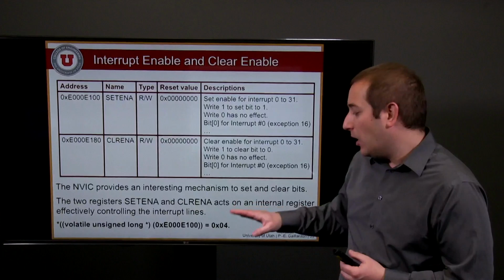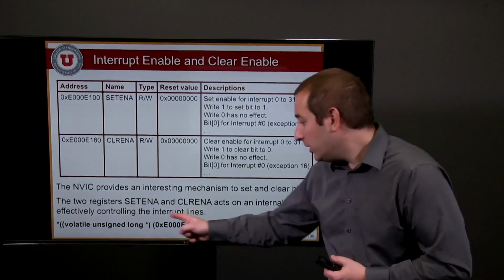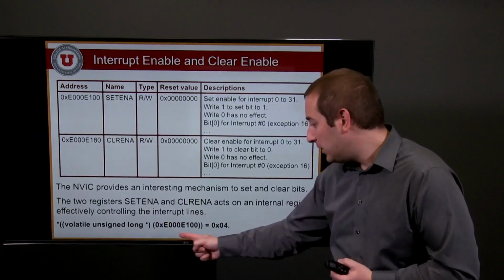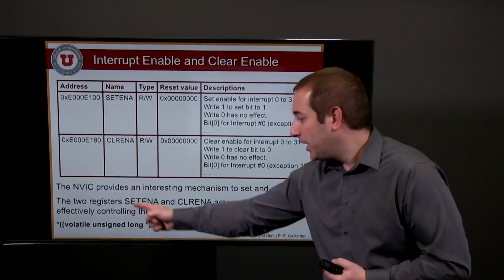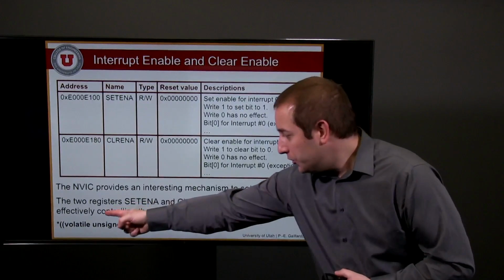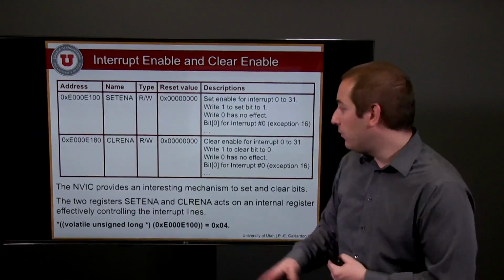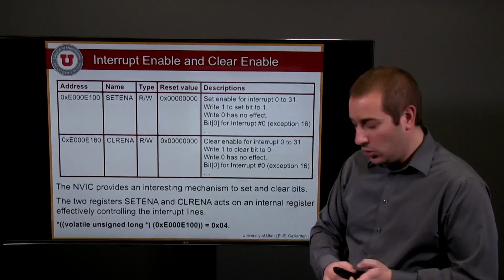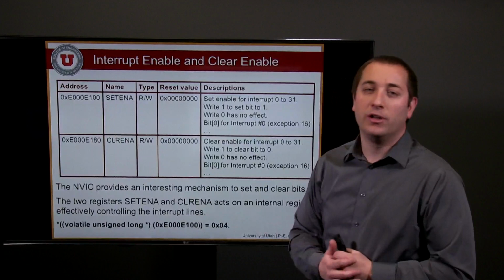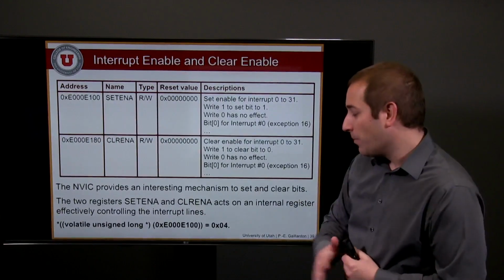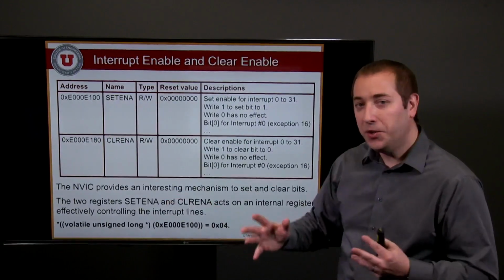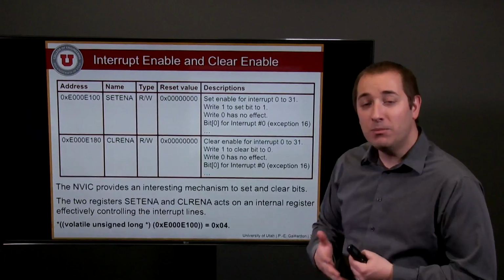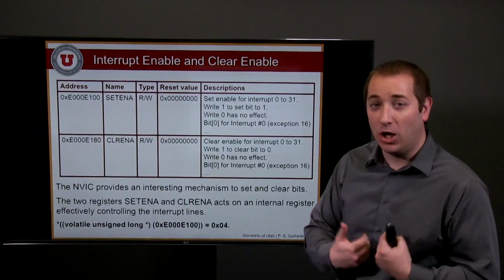How do you access this space? Well, as I said, you could directly perform some direct addressing. So you'll have the address of your register that you can cast into a pointer. You'll dereference this pointer and you write whatever value in order to clear the bit of interest. I would like to point you to this volatile keyword that I introduced a couple of lectures ago. The volatile keyword here tells our C compiler that this register can be modified by another mechanism than us.